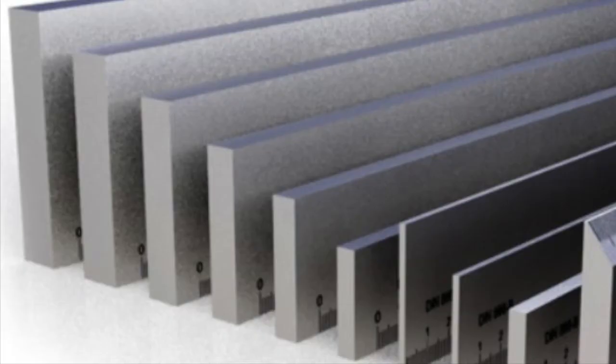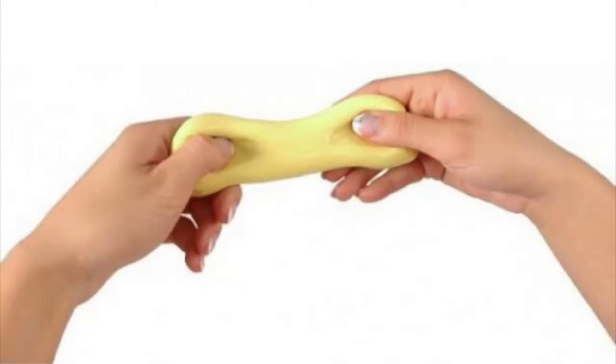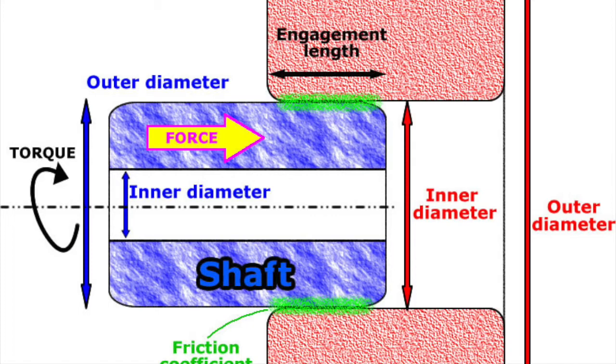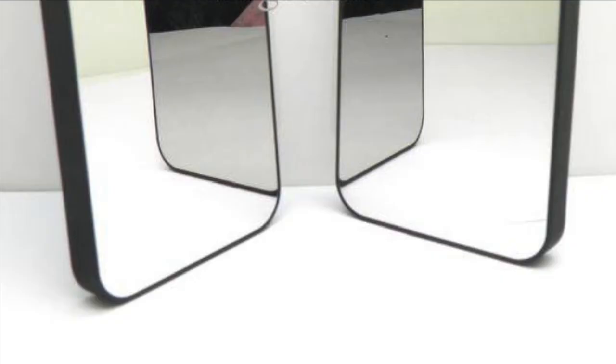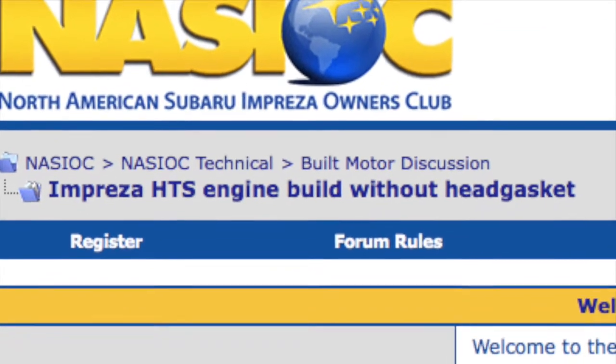The reason that two metal surfaces don't bond together naturally, of course, is because metal is a lot more rigid than a gasket. If the two surfaces were pliable, they could be squished together and a seal would form there, but since metal is not so pliable, you need to have the gasket, or in this case, machine them microscopically flat, as we just explained. Now normally what you'd expect is that if you put two pieces of metal together, even very close fitting metal, that liquid would still leak out. But if you take two completely flat pieces of whatever material, you might be surprised to find that it is in fact possible to seal even against liquids and gases without a gasket or seal.